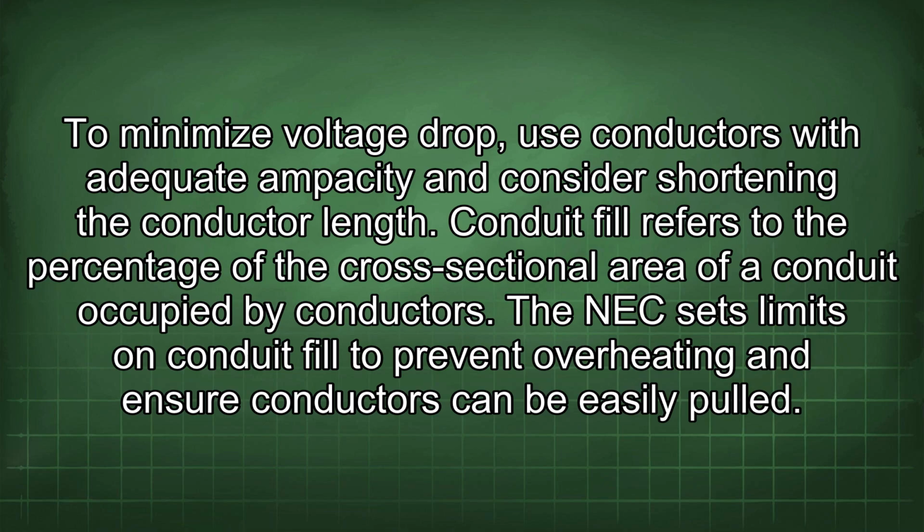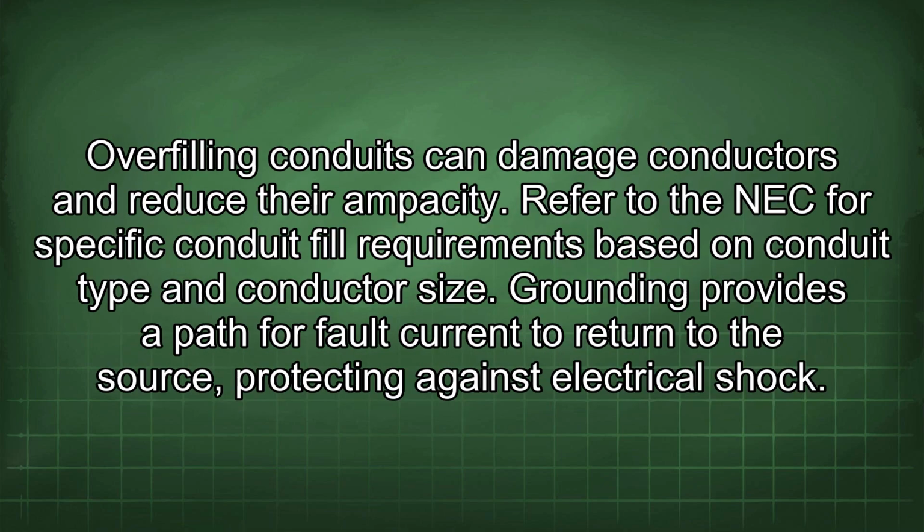Conduit fill refers to the percentage of the cross-sectional area of a conduit occupied by conductors. The NEC sets limits on conduit fill to prevent overheating and ensure conductors can be easily pulled. Overfilling conduits can damage conductors and reduce their ampacity. Refer to the NEC for specific conduit fill requirements based on conduit type and conductor size.